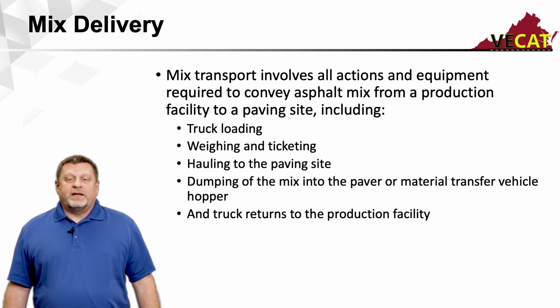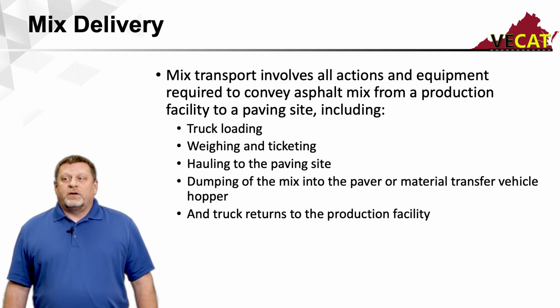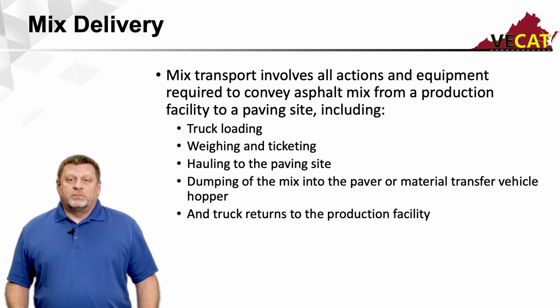When you're hauling it to the paving site, you don't want to be stopping for any reason. We're not going to take a lunch break while we've got a load of asphalt in our truck. When you get to the point you're going to dump the mix into the paver or the MTV, there's a proper way of dumping this, not to cause the paver to bump or move or create bumps in your final pavement. And like I just said, once we've emptied our load, that truck needs to head back to the facility to do another round.